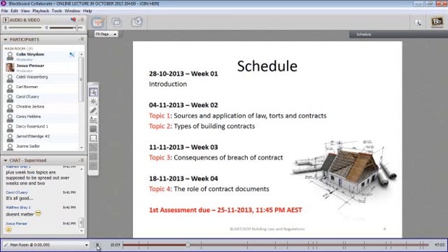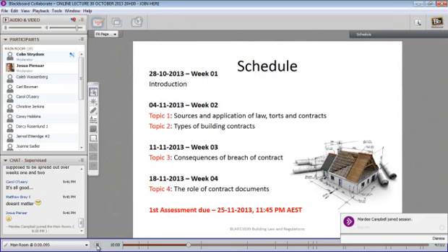Another important part of that is the contract conditions. Some conditions could be fairly straightforward, like no noise allowed on sites. Others could be, it all depends. And then you also end up with any other documents like geotechnical reports, which is soil testing, basically. Asbestos reports usually also form part of that, especially if it's a renovation, and so on.